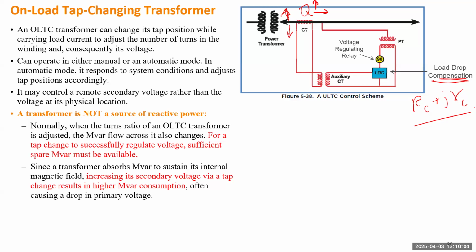Because when you design this negative feedback control, you determine moving up will bring more Q to the secondary side and then support voltage. So you just keep that same direction. But if the primary side is very weak and the Q cannot increase, like the primary side almost reaches a limit, the tap doesn't know, it will keep moving. It can go the opposite way. To really explain what happened, we can wait until the voltage stability session, because that will cause some bifurcation issue, which means the direction of the control actually changes, but the controller doesn't know.